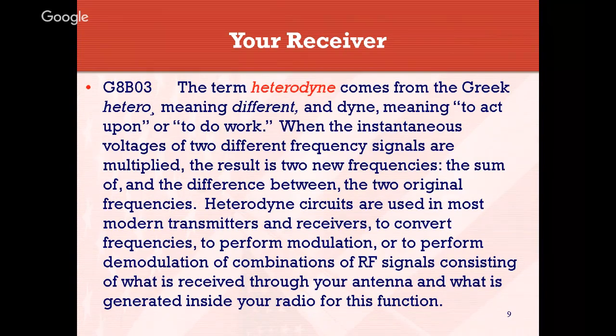And between those combinations, and depending on how your channel selector worked, it would select one crystal from one side and a crystal from the other side to generate the frequency that it needed for, say, channel one or channel two or whatever.